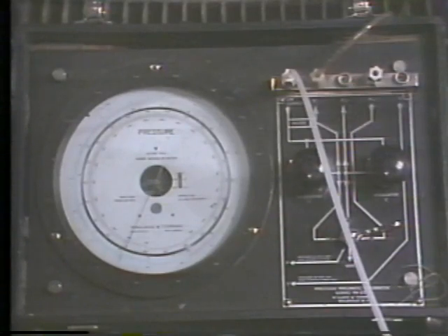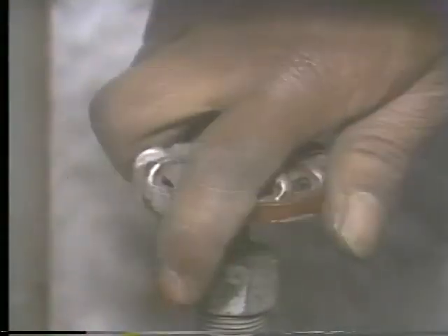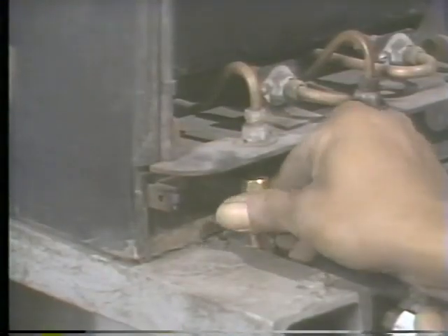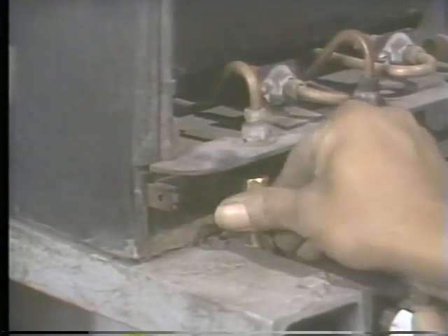Before this instrument can be connected to the positioner and the plant air supply, the regulator should be turned completely counterclockwise so that no air flows through the instrument until it is needed. Next, the technician locates a source of supply air and closes it off so he can connect the manual loader to the air supply. Then, the technician connects one air line from the manual loader to the air supply and another line from the loader to the control air input of the positioner.